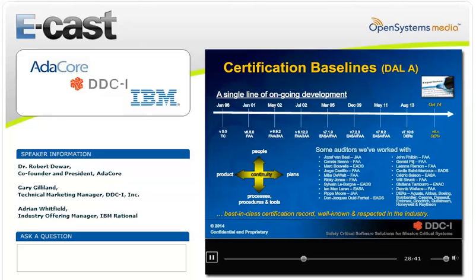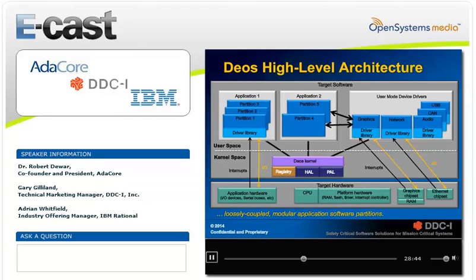So here's a high-level architecture view of DIOS. As I said before, it's fully modular microkernel architecture. The DIOS kernel module is dynamically linked with other components to provide the functionality of the system. A BSP consists of some boot code along with the platform abstraction layer, seen here as the PAL, which provides the interfaces to the platform hardware required for the kernel, which is timers, memory, interrupt controllers, etc. The hardware abstraction layer, HAL, provides CPU family interface to the kernel. So for PowerPC or x86, there may be a difference, but it'll run for the family of PowerPCs.